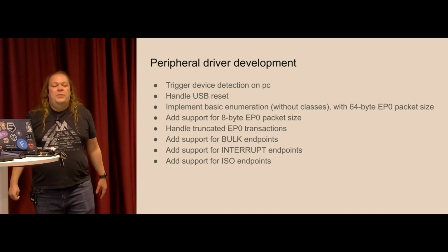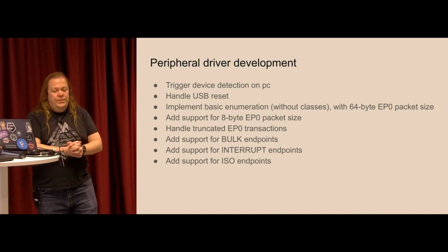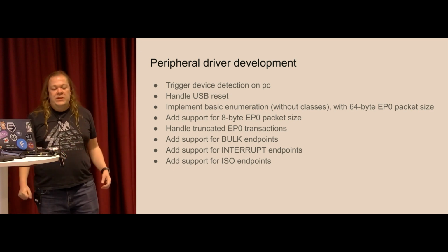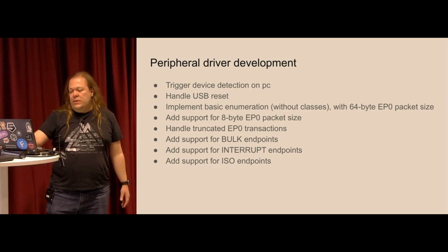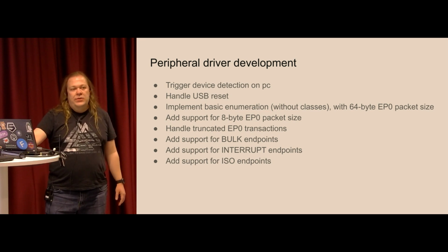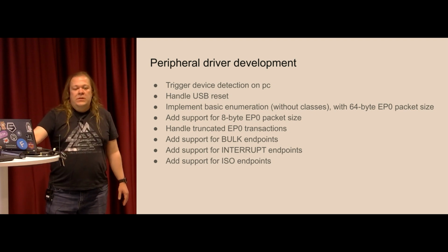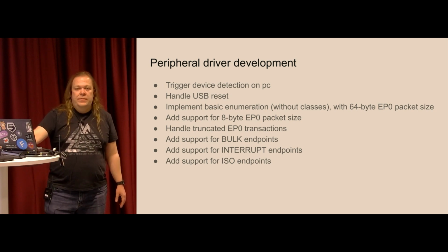And what it takes to make a USB driver, for example. I will just go quickly through this to make you understand roughly what it takes. So when you have just a microcontroller and you don't have a driver for it, or you have your FPGA stuff, something that is not supported yet, the first thing you want to do is to make the host detect your device.